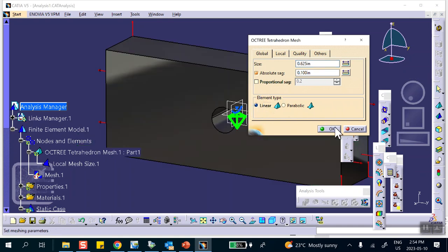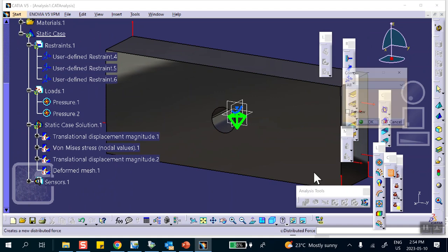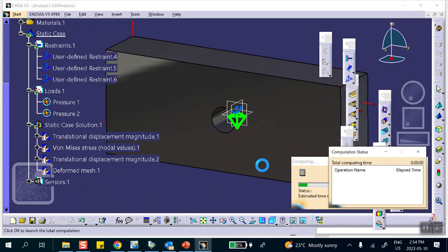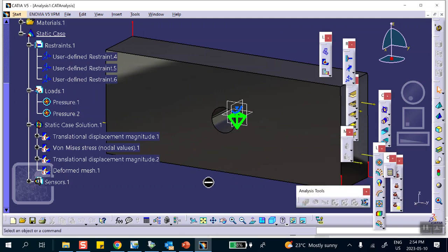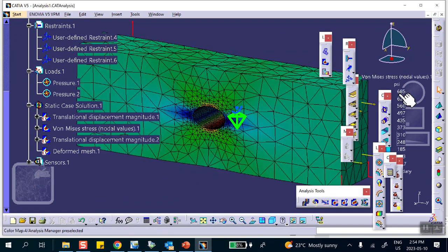And see what the effect is. Remember, here it was 780 at the stress, so run it. 780-ish, because when we remove the number of planes of symmetry, that's changed a little bit, but not by much. Okay, and let's look at the 1 meter stress. You see, 680, that's a lot of change. Going from linear to parabolic, it gave you about 10% difference.